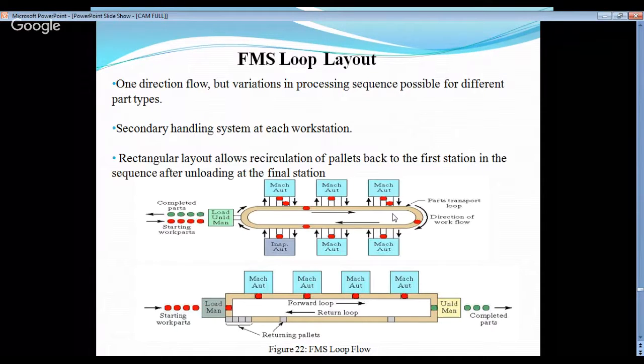It increases the flexibility of the system, as if one of the workstations is skipped or we need to perform an operation after a certain operation has already been performed on the workpiece, we can move the workpiece again in the same path. It will complete all the processes, and then again we can move the part to the area. It is more flexible than the previous layout.